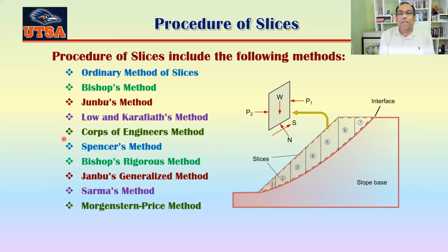And the software can calculate the factor of safety of hundreds or thousands of potential failure surfaces in a fraction of a minute, okay? On the other hand, if you do the hand calculation, just for one potential slip surface it might take 2-3 days. So that's why we usually do this analysis with software, but at the same time there is a requirement to show that calculation with hand computations or Excel or something like that.